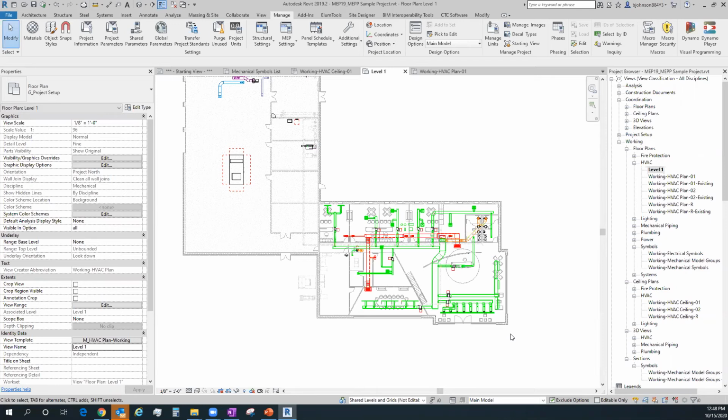So then I started thinking about it. If we've upgraded all these templates over and over again and not actually started with the out-of-the-box template and added our stuff to it correctly, maybe that's a source where the previous version isn't really talking well. So if it's a 2013 template and analytical structural steel properties are turned on and it has nothing in the families to go back to, is that causing my file corruption? It's quite potential.